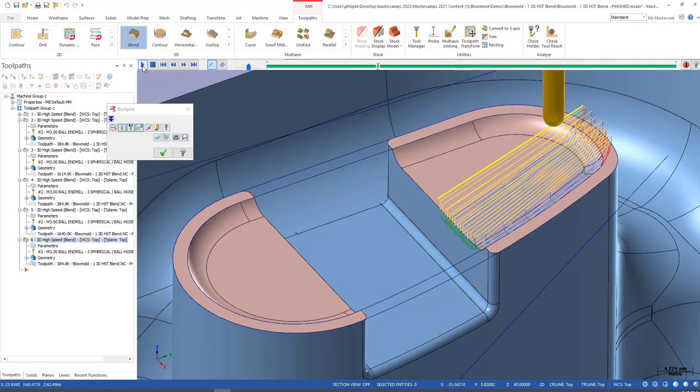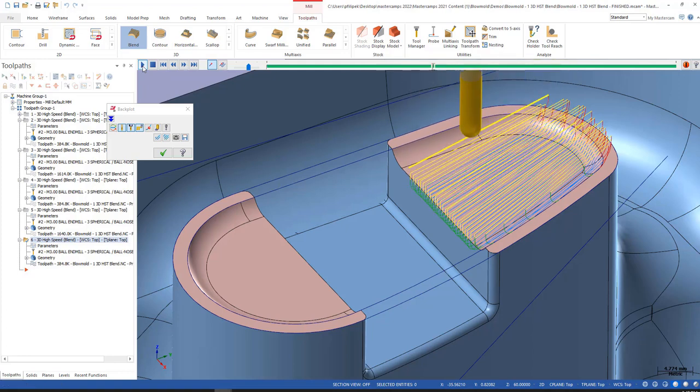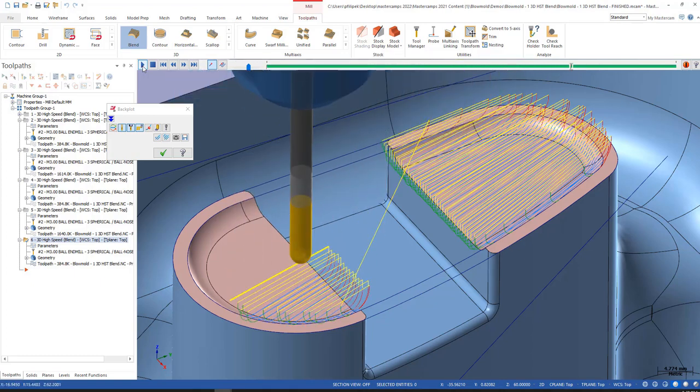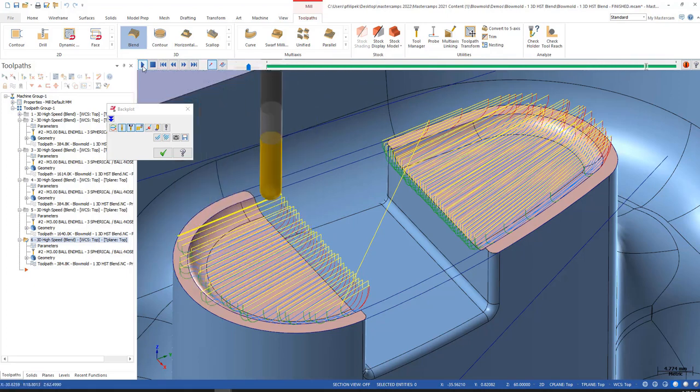So that can be quite a handy little tool there, especially in blend that we didn't have previously. We kind of limited out. Now they're really opening that up with options. So keep that in mind. Definitely check that out. Try to optimize your tool paths, and then try to remember that you can pick a point in blend. You don't have to pick chains. They can be a point. So check that out, and hopefully that can help your cause there.